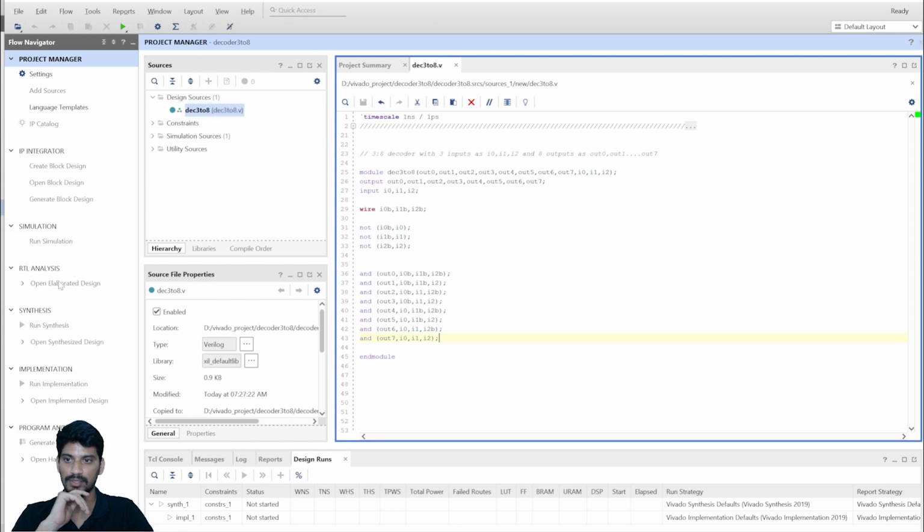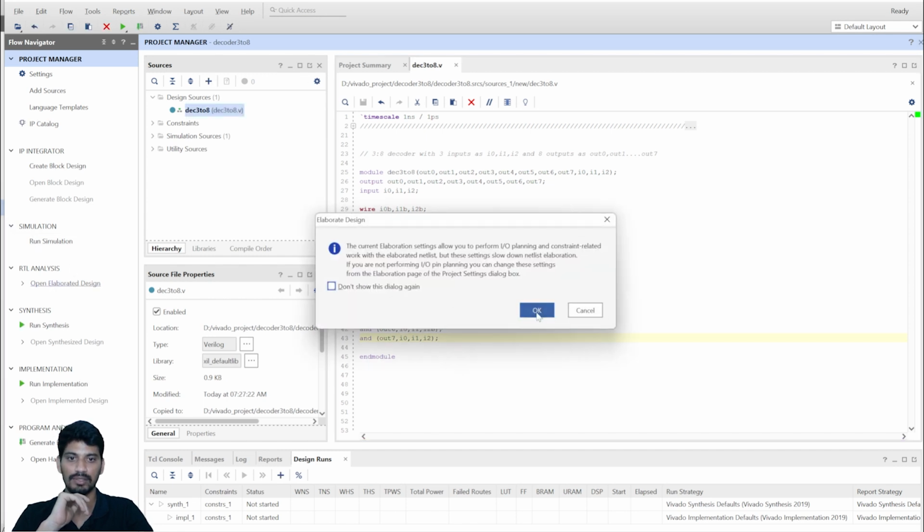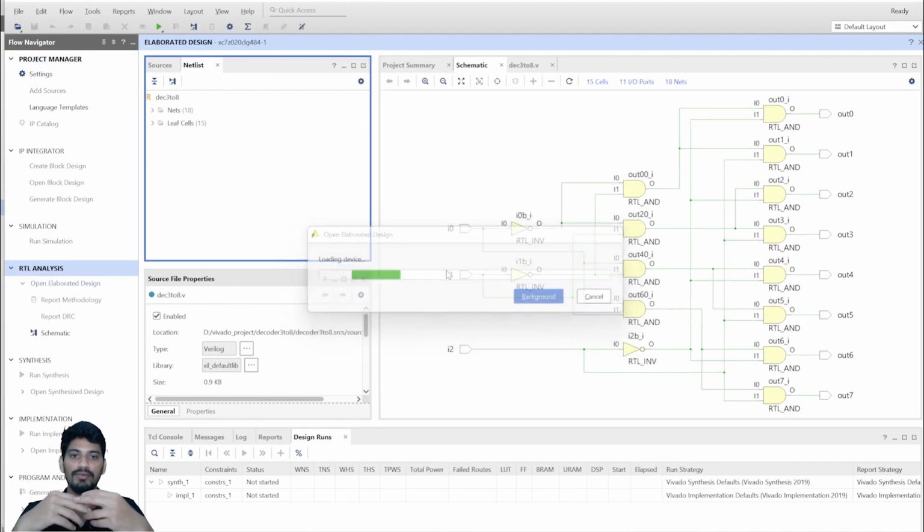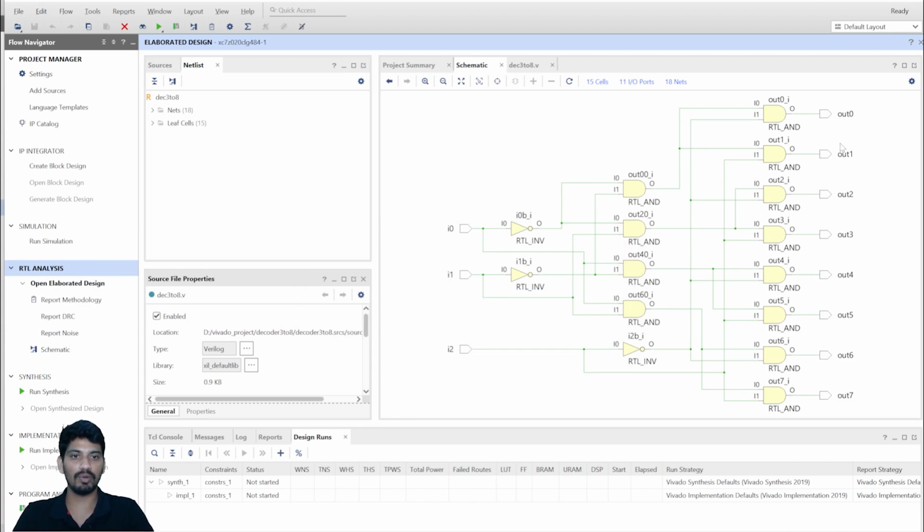And let's see the design of the decoder. We'll continuously follow the same steps so that we'll get habituated to it. Whenever you design something, you always check the design and see whether it is really giving the output that you require. See, I require an output 0 which needs to be mapped from I0, I1 and I2. Right? So the I0, I1 are getting multiplied here, that will get multiplied with I2 here.